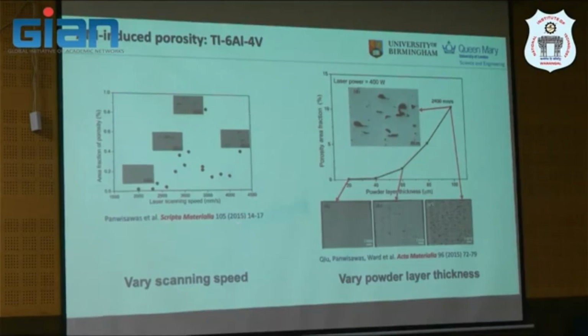Believe me or not, but it's not true, because we use high-speed imaging to check it, and the maximum capacity is just about 4,400 millimeters a second, which means the machine spec is actually wrong. But anyway, this is the big thing we discover as well from the manufacturer point of view. So they said LPBF can increase a lot, but there is a limit, which probably needs to be studied based on the different material you are using.